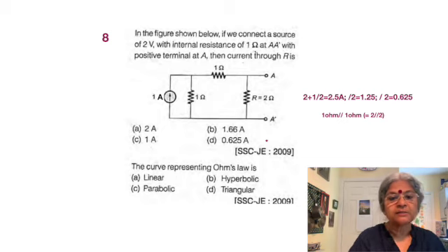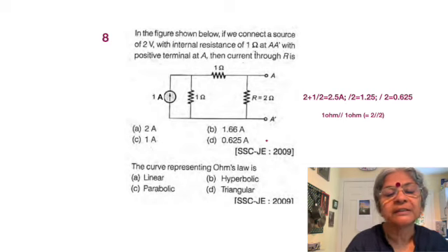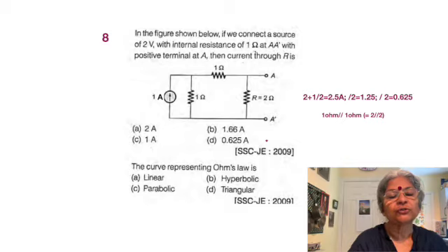So all these aspects can be joined together in the understanding that in total we are having 2.5 amp, 2 plus half, that is 2.5 ampere. Now this is divided into the 2 1 ohm resistors that we have recently created, which gives 1.25. Now the recently created 1 ohm was obtained as a result of paralleling 2 ohms, so again divided by 2. So the answer is 1.25 divided by 2, which is equal to 0.625.